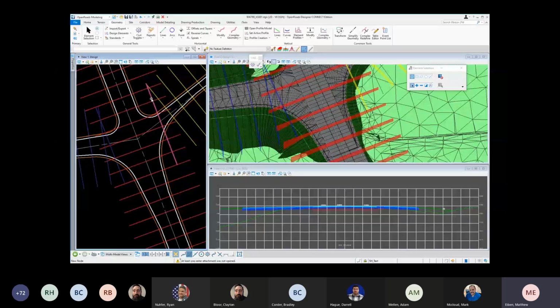And in this case, what I did is I drew in some name boundaries that were 50 feet offset from the center line of this main line here. And I drew those in by cross sections by 2 points, or a name boundary by 2 points. So now they're not perpendicular, obviously, to the center line. So when you did those sections on the ramp sections there, you would need to identify that so that we knew that. But that way, at least captures all of the earthwork that you might need by the end area methods.